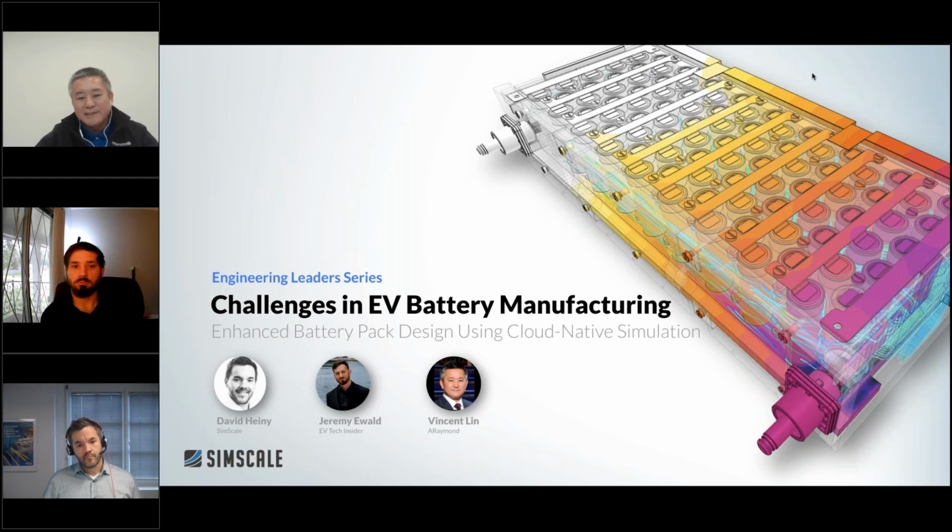And the most important is to select the right connector company. Some connectors at room temperature are good, but over time the resistance will increase, just like your boil down solution, and that will cause a problem. Your thermal system will need to handle something unexpected, like high temperature there, so that might cause thermal runaway or a thermal event. So that's important to know.